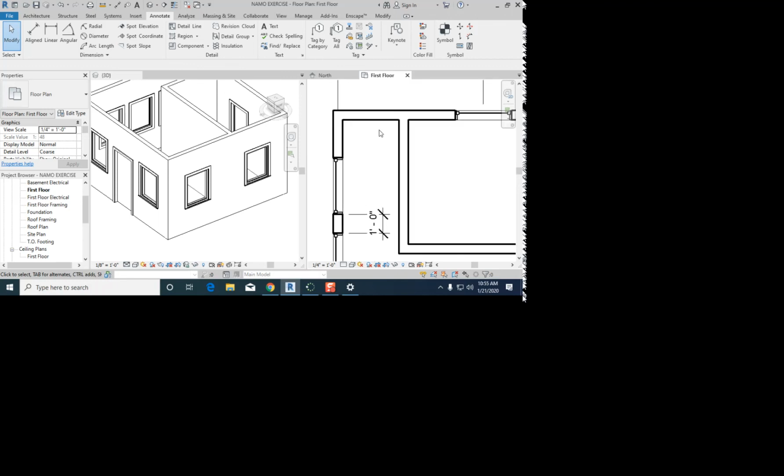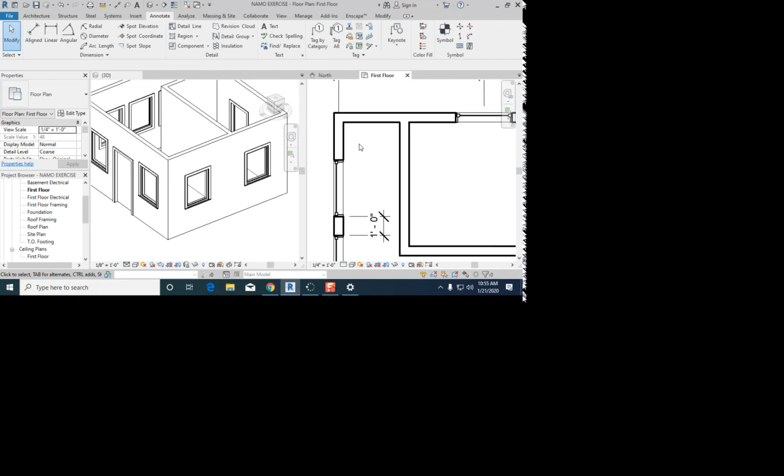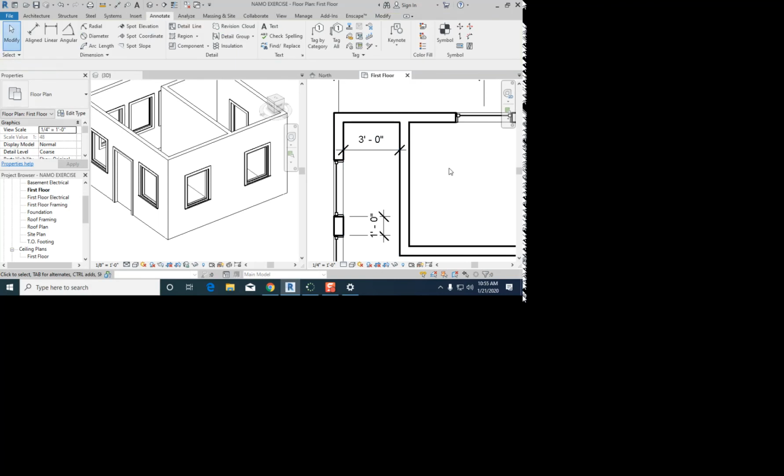All right, let me catch you guys up. If this was a window, what would we do first? We would dimension. What's the shortcut for dimension? DI. Good, so we're going to put a dimension here first. So I had 3 feet, that's pretty good, it's ADA code. Do I want 3 feet? I want 4.